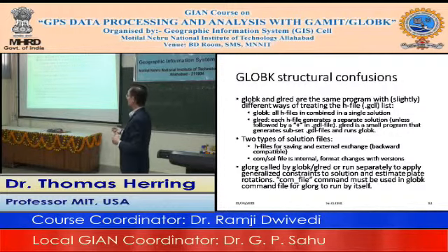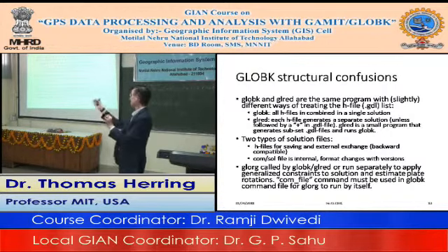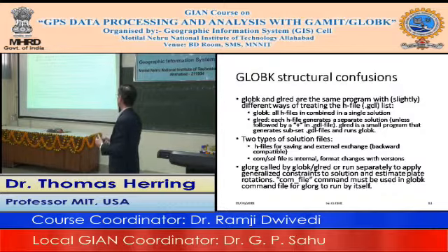When you run GLRED, nominally each of the H files is processed separately and generates its own solution, although there is a syntactical technique you can use where you add a space and then a plus sign at the end of the name, and that allows you to add small blocks together. We take advantage of that when we're doing network combination processing, etc.